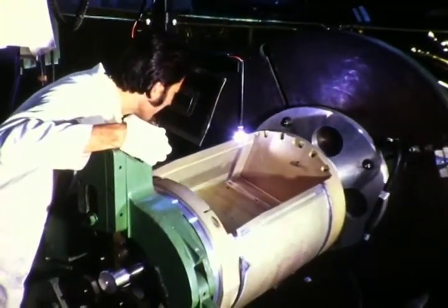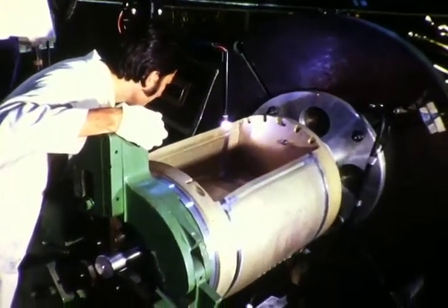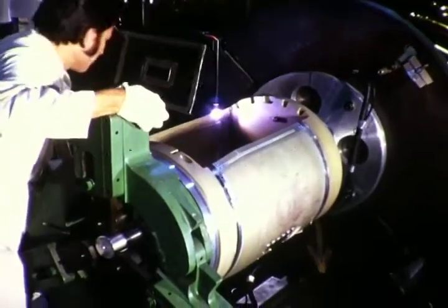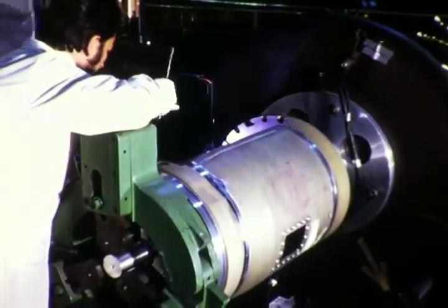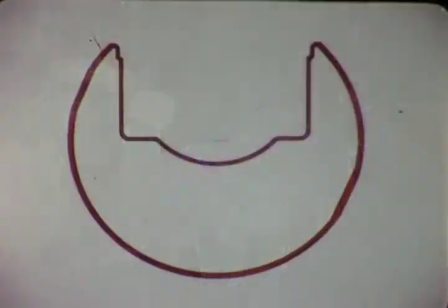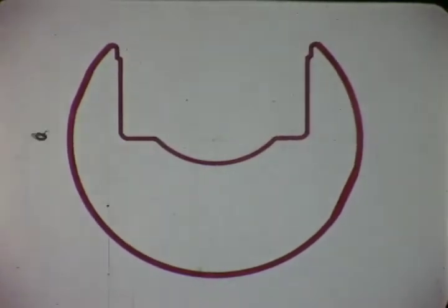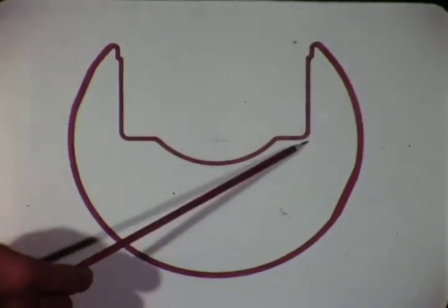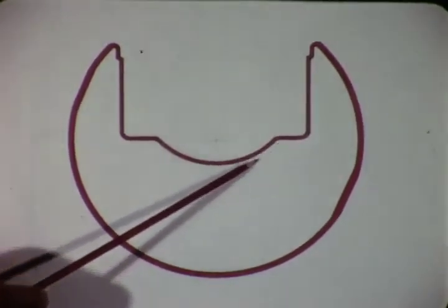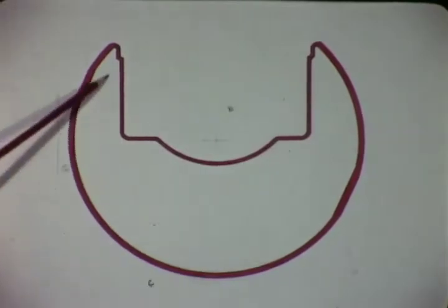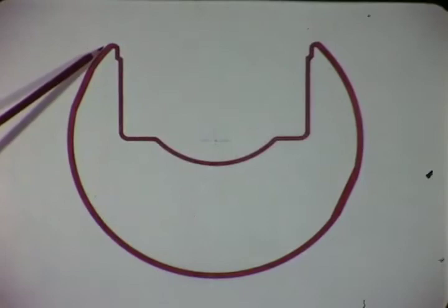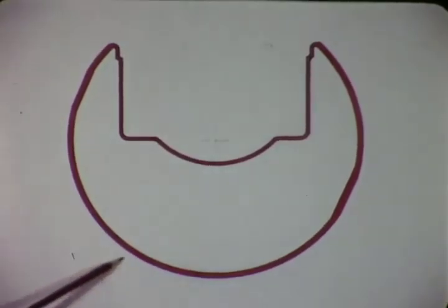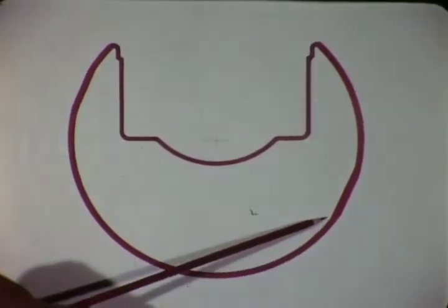At the Convair division of General Dynamics, complex shapes of varying wall thickness are now being welded by an automated system employing direct computer control. This is a graphic cross-section of the cruise missile aft body, aft bulkhead weld joint area. It contains many curves of various radii, step-type jogs, severe corners of varying thickness, and a continuous constant radius with areas of tapering thickness.